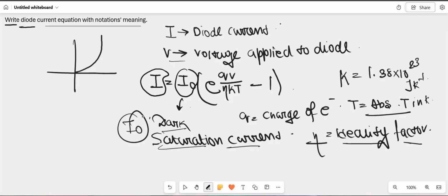This parameter is a characteristic of the diode under consideration and indicates the amount of recombination which occurs within it. In a PN junction, the junction can be forward biased or reverse biased. In forward bias, electrons generally move from the N side to the P side, and for that reason, current flows through the diode.